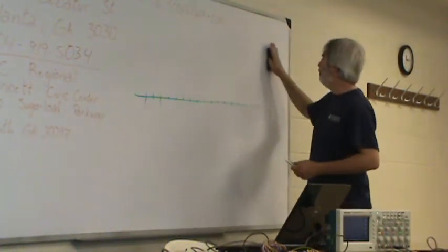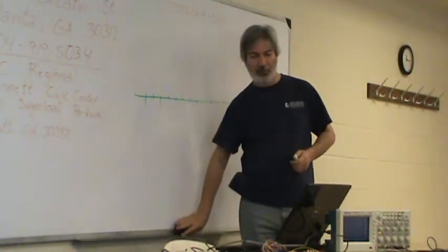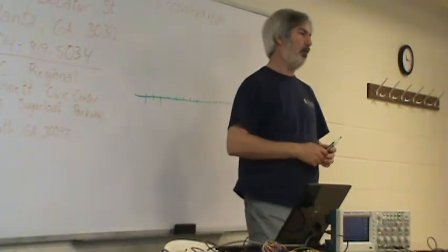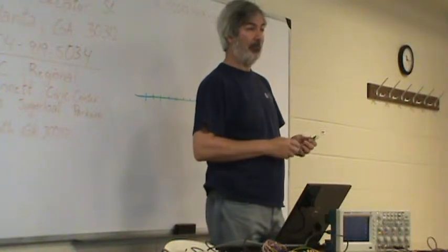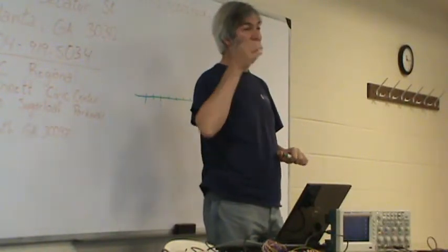Another thing that you will frequently want to do with a scope is check your power supply pins. What happens to a circuit if you don't have good power? Very quickly, your system will become erratic or flat, not work.